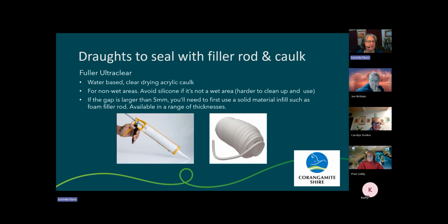There are lots and lots of drafts that you can simply fill with filler rod and cork. If any of you were at the in-person session, you will have seen probably a little tube of filler rod. It's this stuff. It's just foam, and it comes in a packet with a whole roll of it, really cheap. And why you use that is when the gap is more than 5 millimeters, you can't use this cork on top of it to fill the gap, unless you've got something in there for the cork to then sit on, so to speak. So first of all, work out where your gaps are.